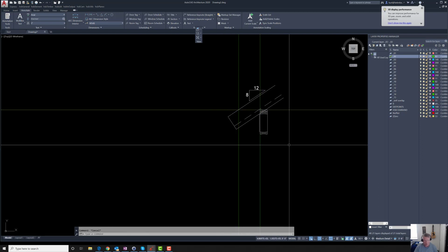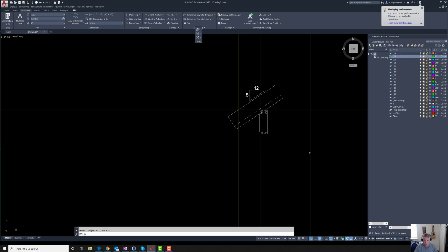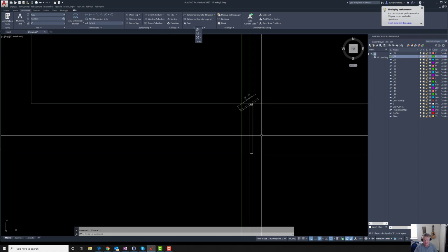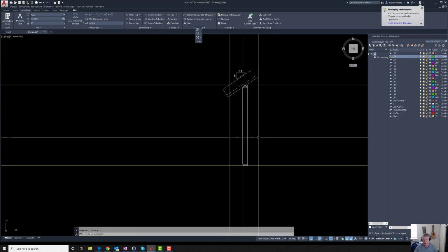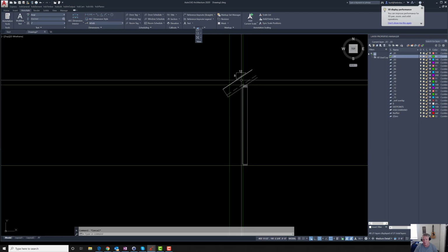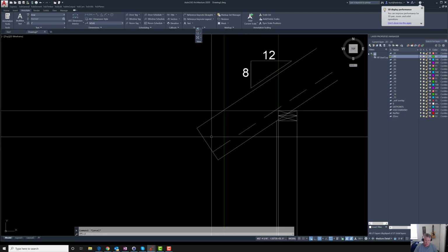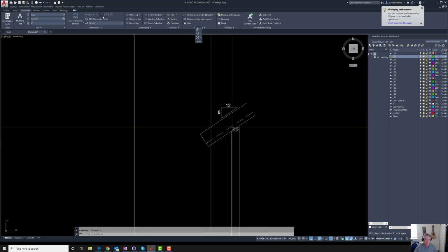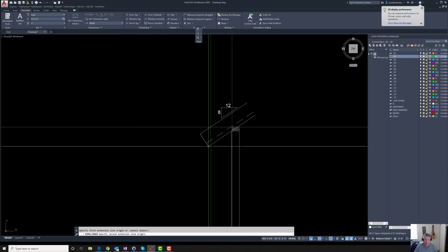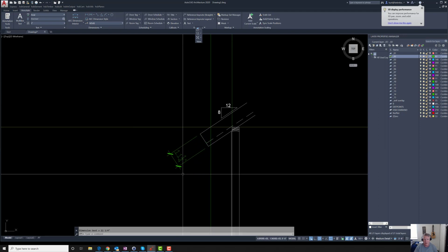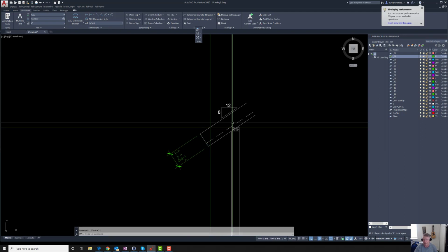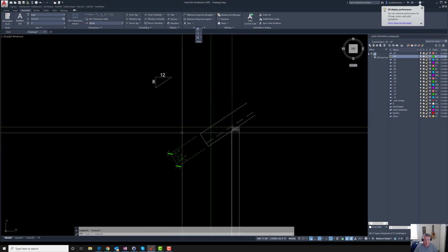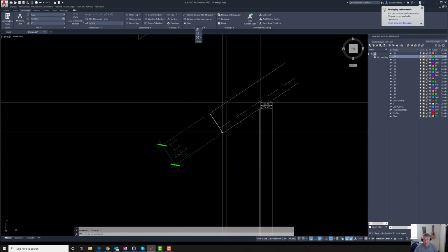Now I've placed my wall on the grid line, and I will quickly just stretch the bottom of this wall down there. So now I've drawn what would be a typical 92 1/4 stud, 8 foot 0 3/4 overall height. For my fascia overhang, we typically use 2x12 rafters out in the west and in the mountains to get the strength we need and the insulation cavity that we need to meet the energy requirements. So you can see that for ALS dry sizing at timbers, that's going to be 11 1/4 inches deep.